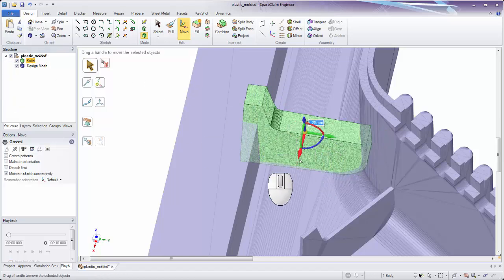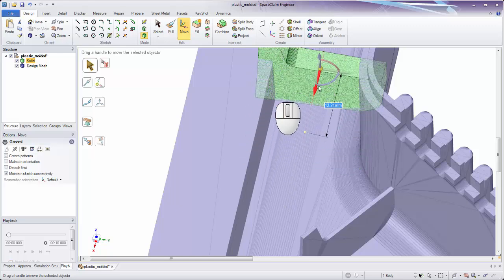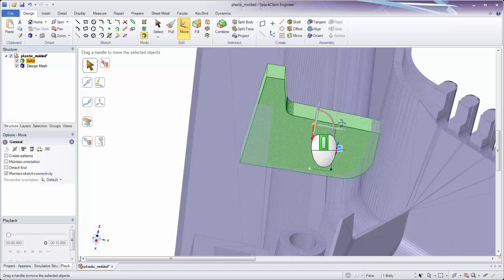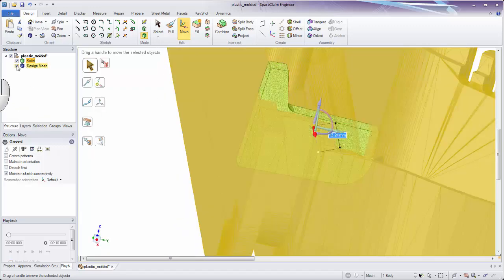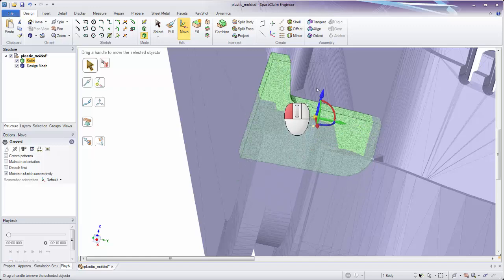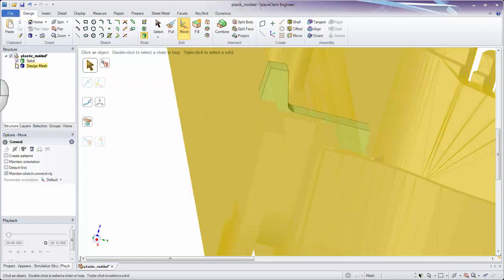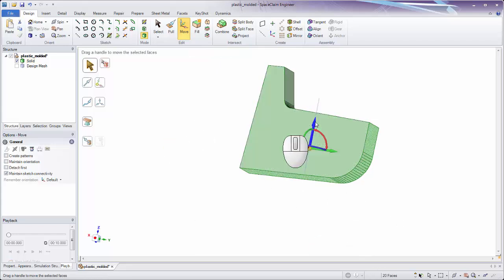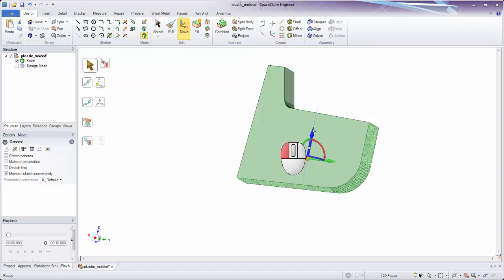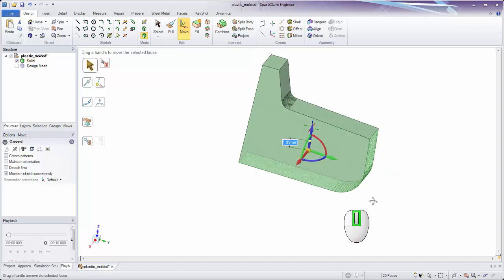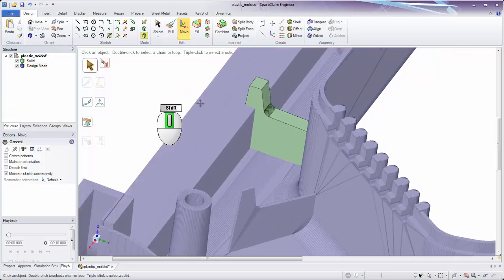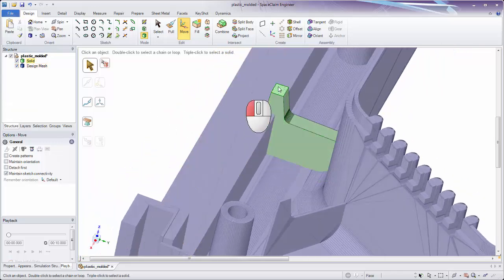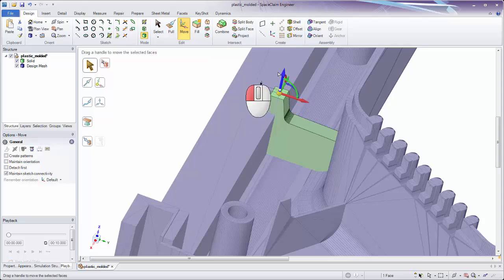And the key thing is that we want it to intersect or interfere enough with the existing part. Now, to do this, we have a few options. We could take the entire body and move it up or down so it's into the assembly. Another thing we can do is grab some of the faces, say here with a box select, and just go ahead and use the Move tool to extend them down. So it's always a good idea to make sure that you have adequate interference between the different bodies. And maybe we don't want this as tall, so we could always make whatever modifications we want to it, even using the Up To command to snap this to some other geometry in the model.